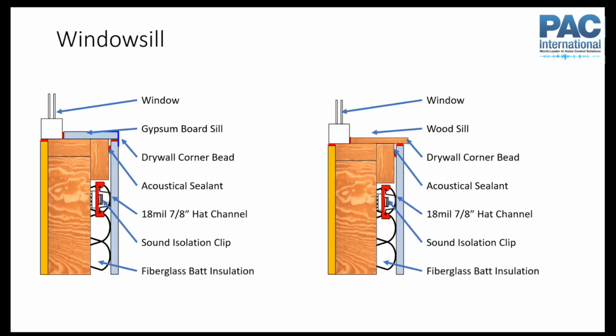And that's what we've done at the window sill, because the sill itself is especially tricky because it's something that's going to have probably load on it, whether it's just people putting some plants in their window, or my kids climbing up in the windowsill to get a better view outside, something like that. So here you add some blocking to support that sill and bring that support out to the drywall that's there at the wall.